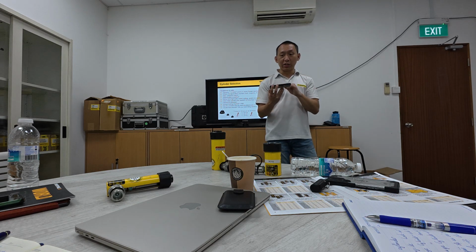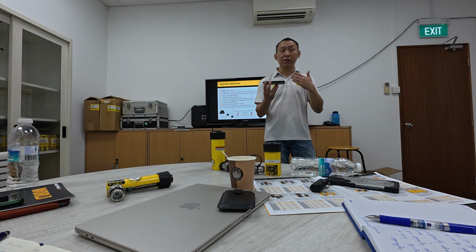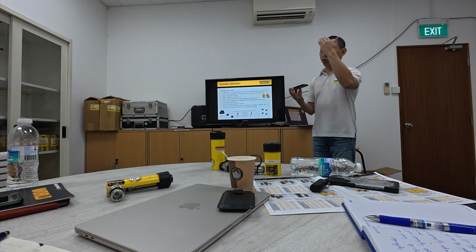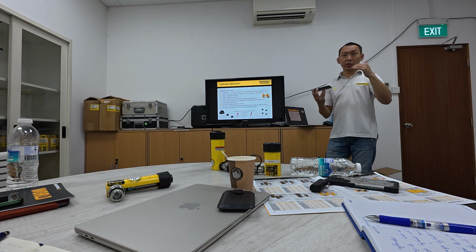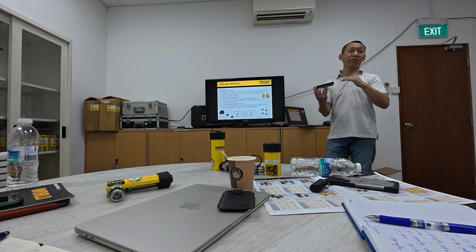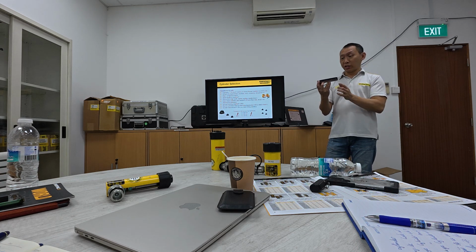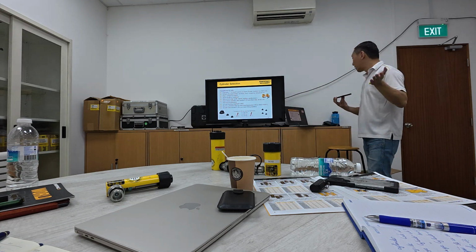Okay, but you can highlight what's the risk involved as an example, because if let's say there's a load shift, then your cylinder cannot take it. Then maybe we can recommend to the customer to take a higher capacity so that there will be less risk. When you have a bigger safety factor, the operating pressure will be much lower. For example, if this is a 1,000 ton, you have 2,000 ton, you are operating at half the pressure. You still have a lot of safety buffer in case anything happens, you still can move. So these are things that we have to consider when you advise the customer.